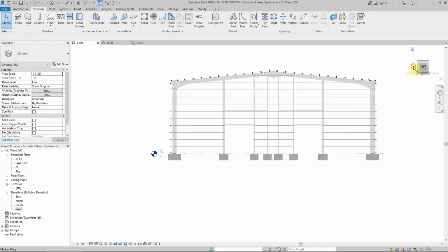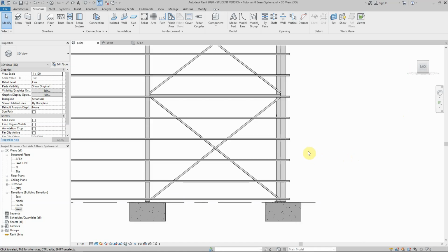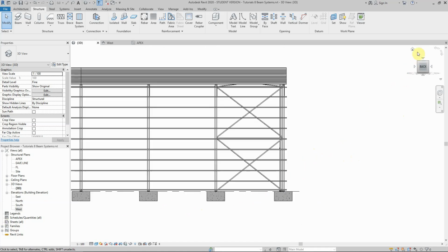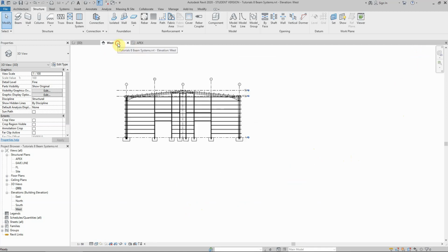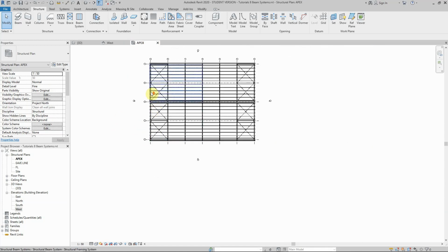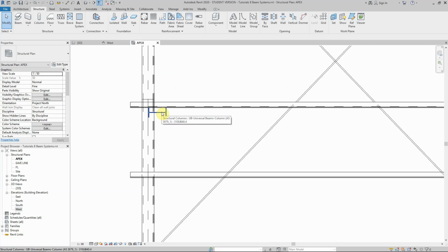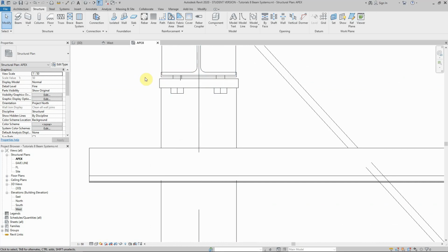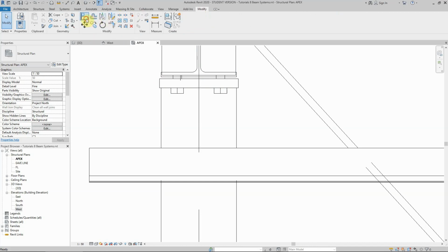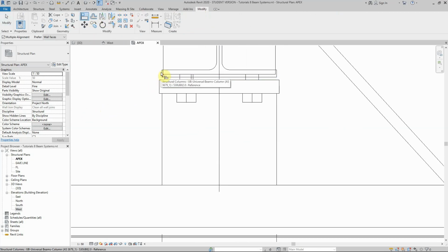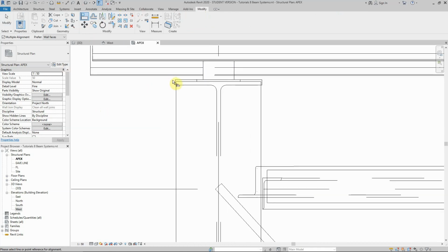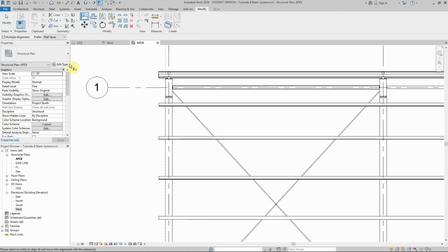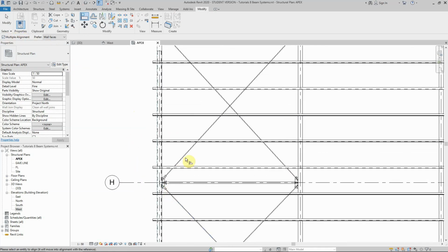Now let's just double check the level of these girts. First of all, let me fix the end wall or the short walls columns. These walls here, the columns here, this column here for example, should be sitting in line with the outer edge of this column here. For some reason when I was drawing maybe the beams, I moved them. That's fine, we can easily just go to modify, align, and this is my reference, the corner of the corner column. This is the line, and I will make sure it's multiple alignments. So I'll align multiple members.